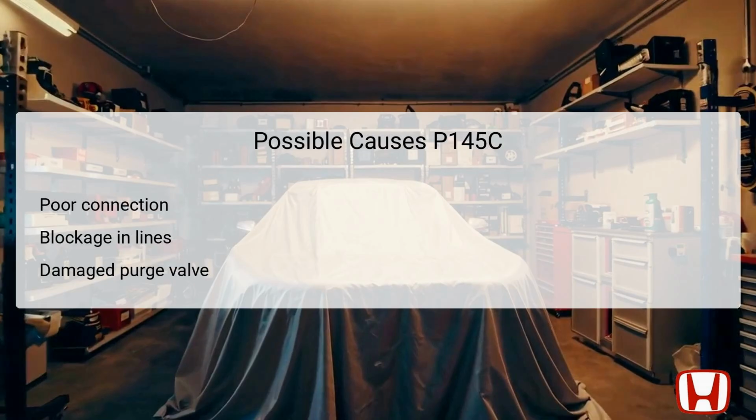Several potential causes can lead to the triggering of DTC P145C. A poor electrical connection at the EVAP canister purge valve can prevent it from operating correctly, thereby resulting in malfunction. Thorough inspection of the connections for corrosion or looseness can reveal underlying issues.